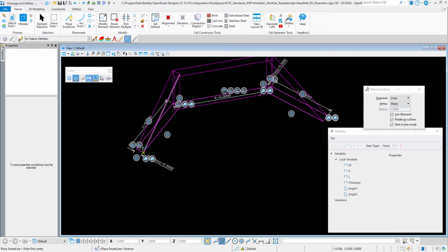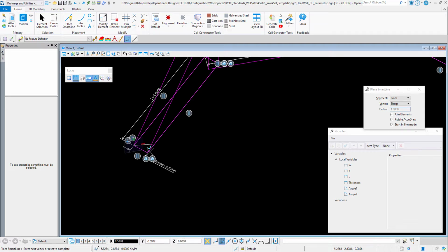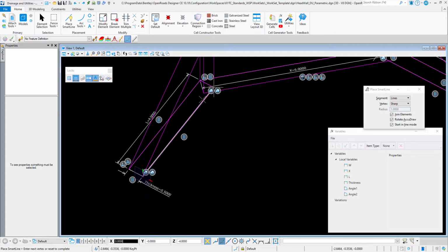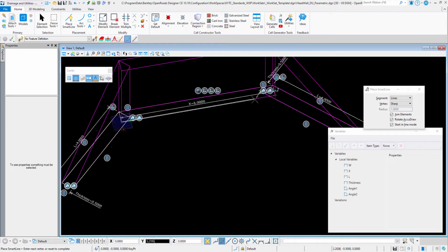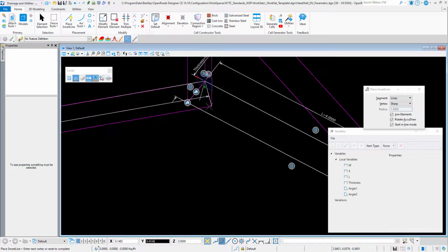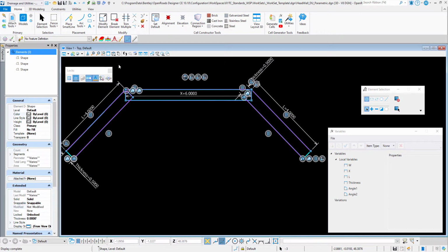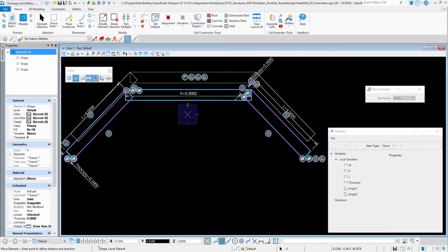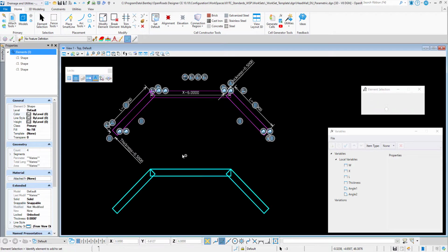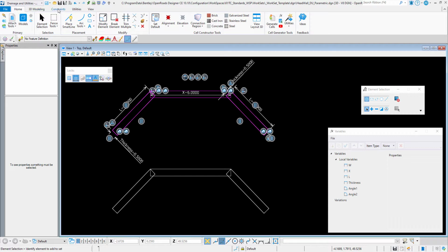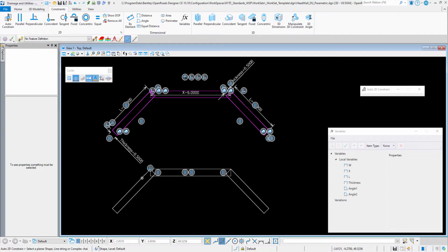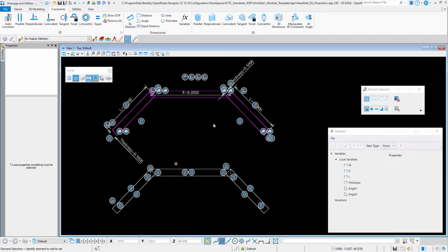Now the next thing I'm going to do is trace over the bottom lines for this collar. And because I'm tracing over them, I know that they're all going to be on the same plane. And so when I apply some of the constraints that I might have later on, I'm going to be fine. I typically go to top view, select all of them, and then move them. And as long as I don't move my Z value as I move them, then they should all be at the same plane. And just like with the others, I'm going to make sure that I constrain them all. Perpendicular and parallel. Auto constrain helps a lot with that.